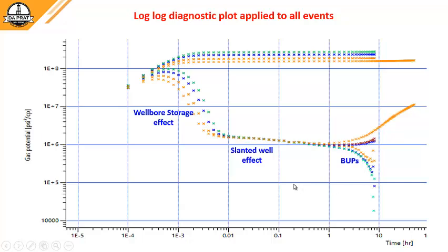I mean, you reach the static pressure, and the drawdowns confirm that it is a sealing boundary and not a constant pressure boundary. You may say that because the buildup is going down, there is some kind of active boundary, constant pressure like a huge aquifer. But when you do the drawdown, it confirms that it's not dealing with pressure maintenance. It's rather a sealing type of